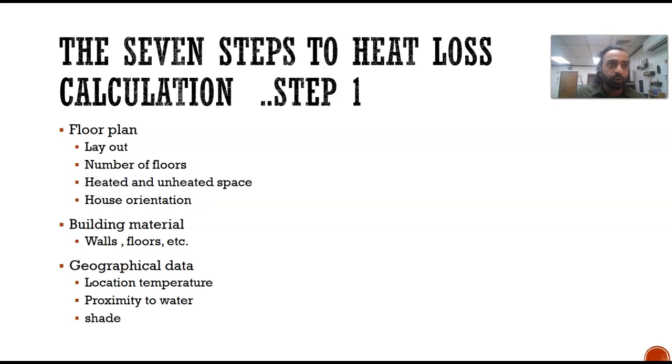It's a very good tool to know which wall is leaking the most heat. Again, we already know that most heat leaks from the ceiling. So it's very important to go and look at the attic and see if it's insulated or not. If not, we might want to recommend that this ceiling should be insulated. I think the recommendation recently from the Department of Energy is a resistance of 32, which is high. So we need really high resistance for the ceiling or the attic because that's where we lose most of the heat.